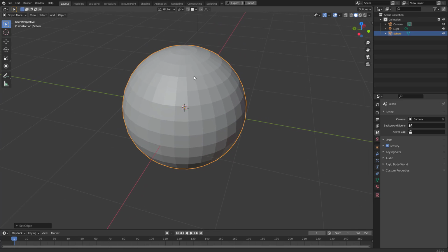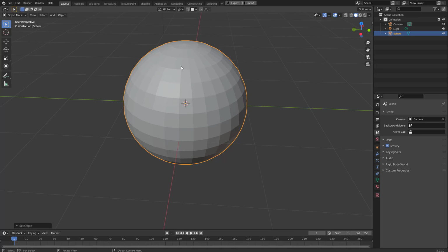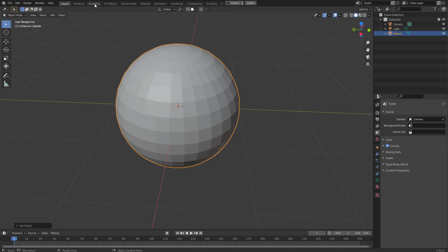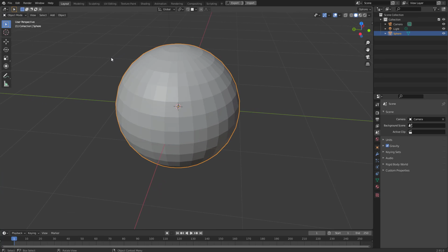Anyway, that is just basic stuff. Let's talk about sculpting, of course. So you need to go to sculpting by going to the sculpting workspace or layout, or you can go here and toggle your mode to sculpting mode. You can also hold down the tab button and start moving the cursor. You can see you can go to those various modes by using this marking menu, or pie menu as it's named in Blender. This is called a pie menu. This is called a marking menu in Maya. Feels similar, but not exactly the same.